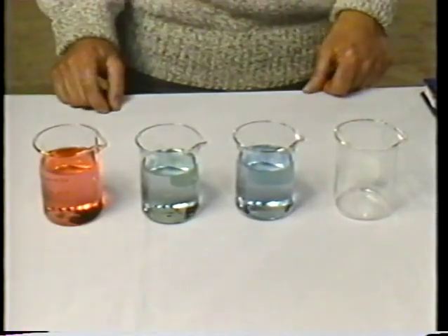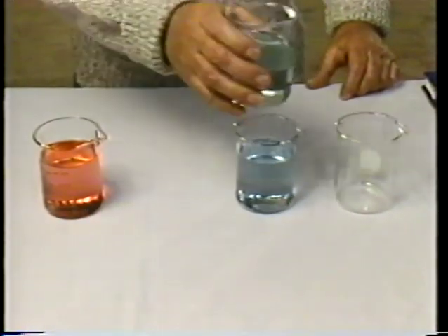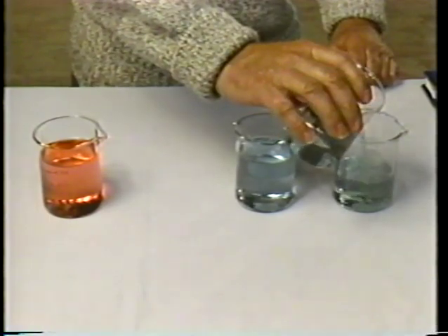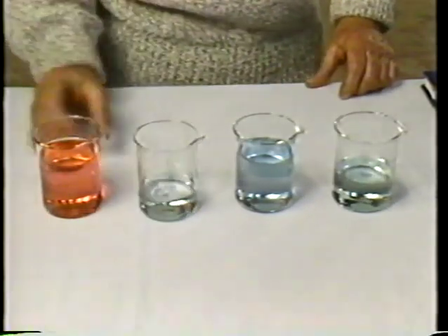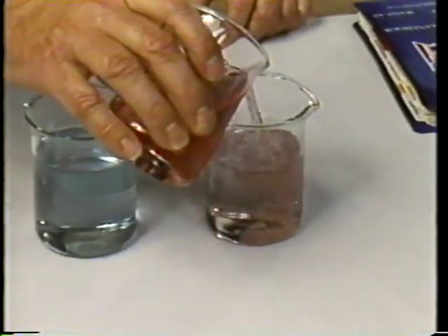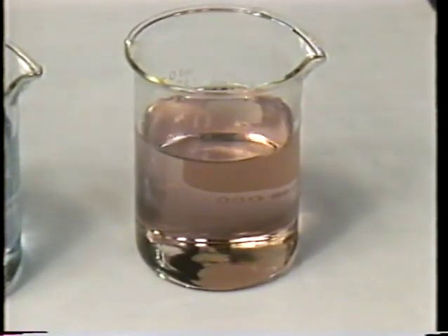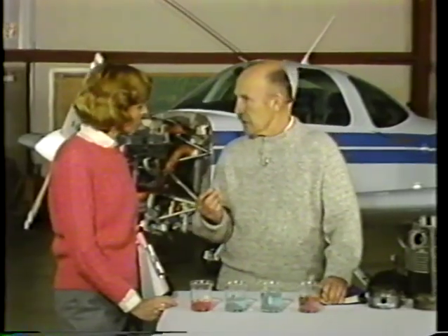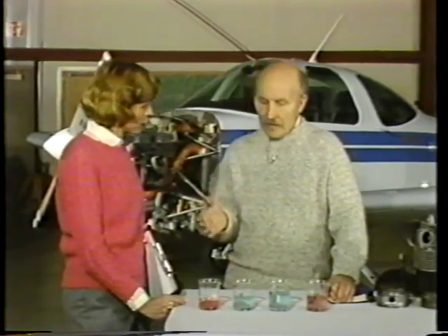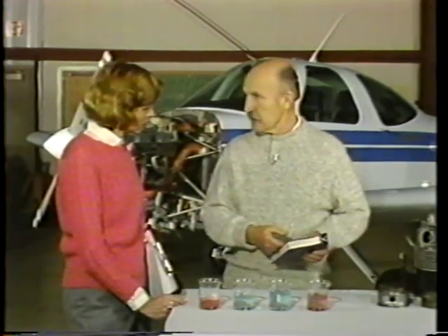Well, the dye put into the fuel is such that if we mix the fuels, and I'll show you how that works, the color will change. The color tends to disappear, and the liquid fuel then should go from, say, clear to a straw color. So when you take your fuel sample, if it's clear or just slightly yellowish, then you know it's been contaminated. And again, by referring to the manual on the airplane, you will know if this is acceptable or not.